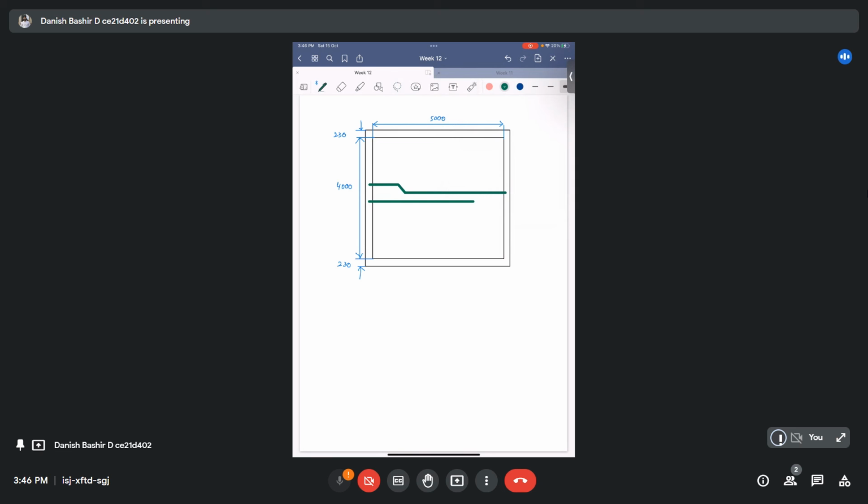This will be a little bit bent there. Okay, this will be bent here. This one. So these bars are 10 phi at the rate of 290 center to center. Okay, these are along the Ly direction.